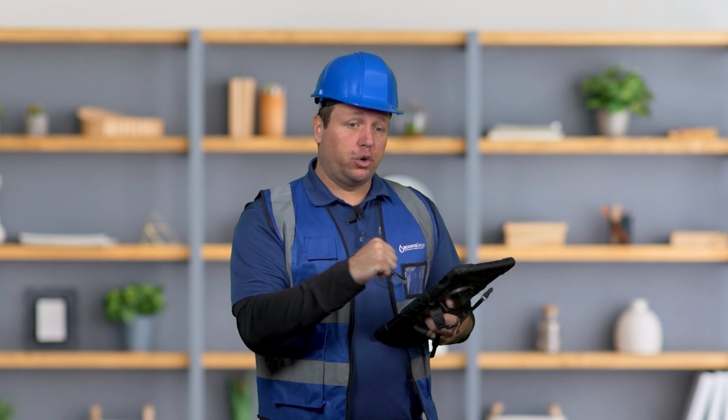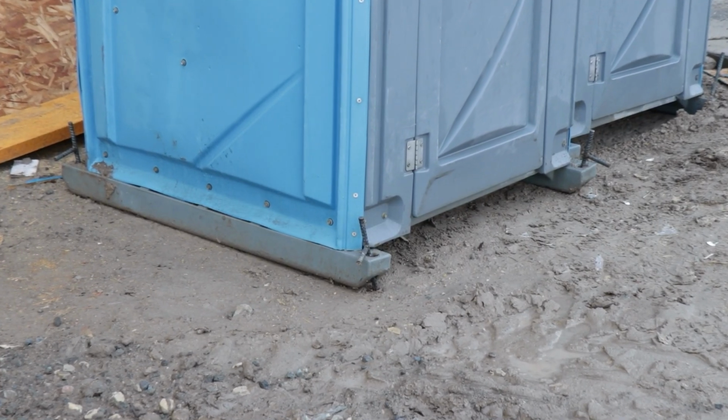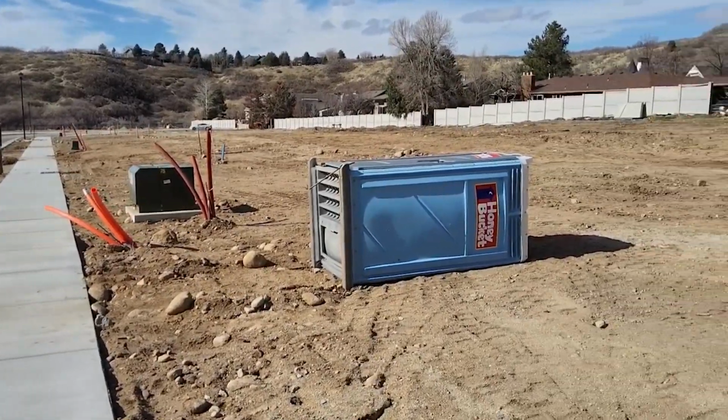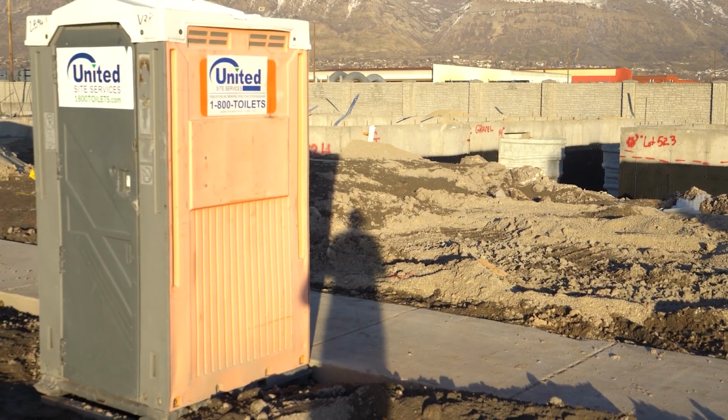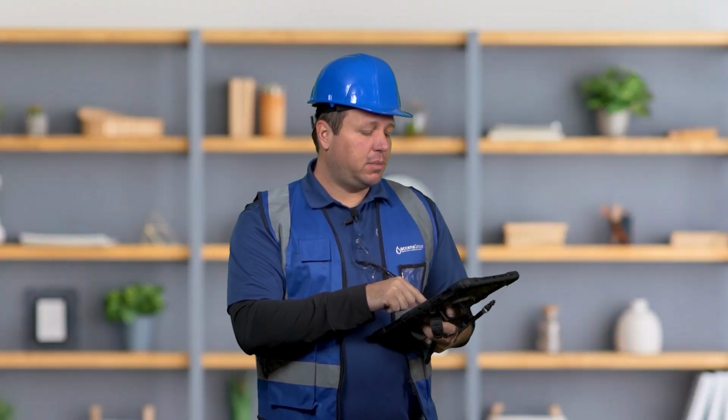Again, if there are inlets that need protection because it's never been installed, or the protections there are so destroyed that they need to be replaced, that would be a corrective action, not a routine maintenance. All right, portable toilets need to be moved or staked down. That, again, is something that we see quite often. Portable toilets are on the sidewalk, they're on pavement, they're not in the correct location, or they're not secured. That would be a routine maintenance, and they would need to be fixed.